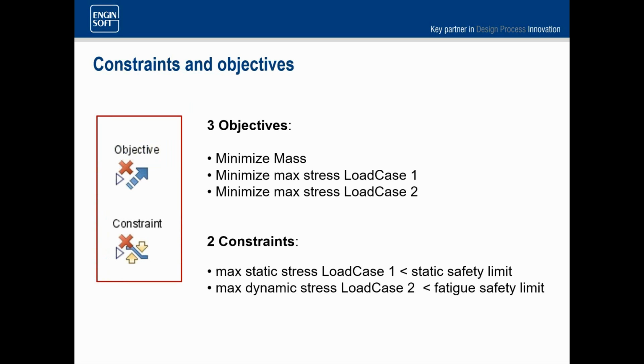In this case, this will be a multidisciplinary, multi-objective problem with three objectives: one to minimize mass, one to minimize the maximum stress of load case 1 and of load case 2. And in addition, we want to apply some constraints to make sure that the static and dynamic stresses are below a particular safety limit as well. And we'll show you how those things are visualized inside modeFRONTIER.